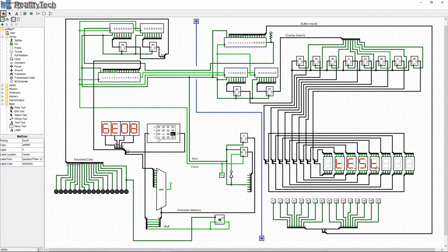So effectively we have 8 segments per 16, 32. We've got 64 individual segments here. We've got 16 buttons here being driven with 4 lines. So yeah, that's probably fairly close to what's going on. We've got a common clock and a common reset line. I don't think the Sony panel does have that. I think they've got separate reset and separate clock lines for everything.